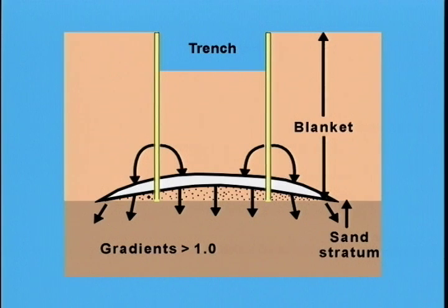Also, there would be a tendency for the blanket between the two cracks to settle into the void space. A sinkhole trench then becomes evident at the surface. The upper parts of the trench walls tend to remain vertical because of seepage into them from the trench. The treatment proposed for the Ludington sinkhole trenches was to fill the trenches and to cover the area adjacent to the trenches with a special filter material.